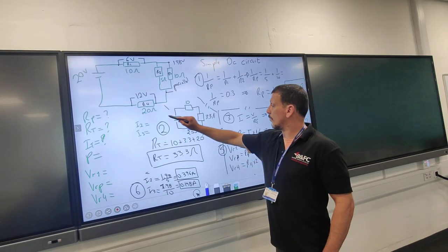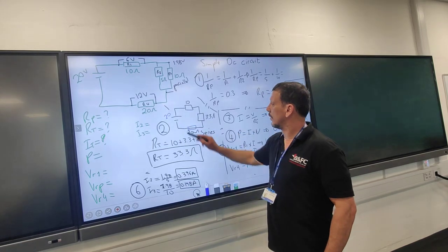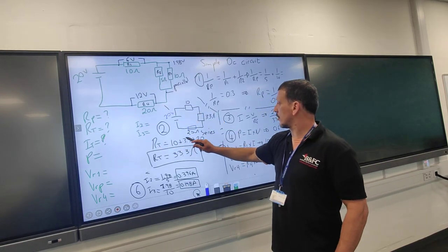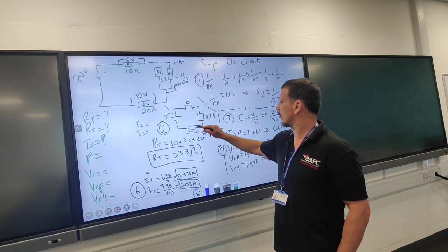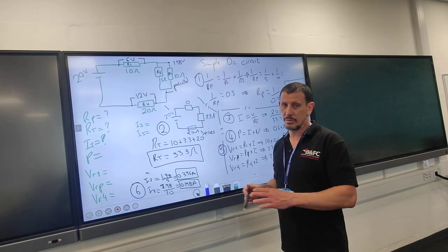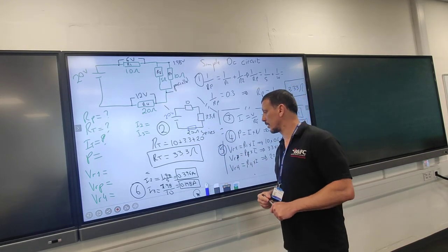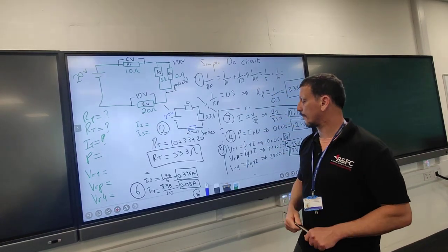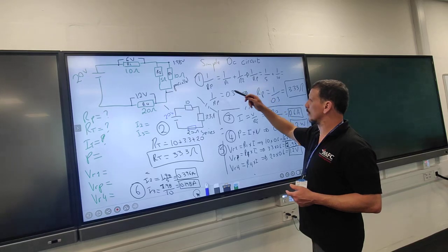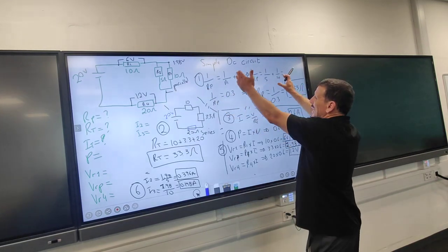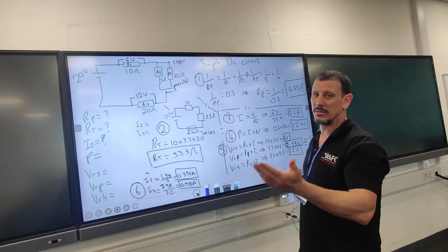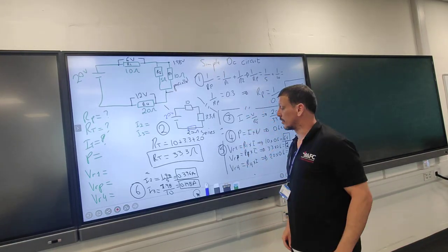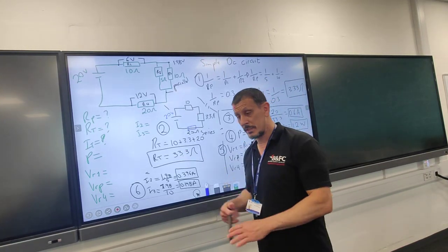With this now, you can work out the total resistance. You just add them up. So total resistance is just going to be 10 plus 3.3 plus 20. This is the protocol for series summation, okay? This is the method, you just add them. Whereas in parallel, you've got to use the formula. Now there's another formula that you can use when you only have 2 resistors, but I like teaching this method because you can't go wrong. With the other method, if you have 3 resistors and you try and use it, it gives you a wrong result. So you have the total resistance.